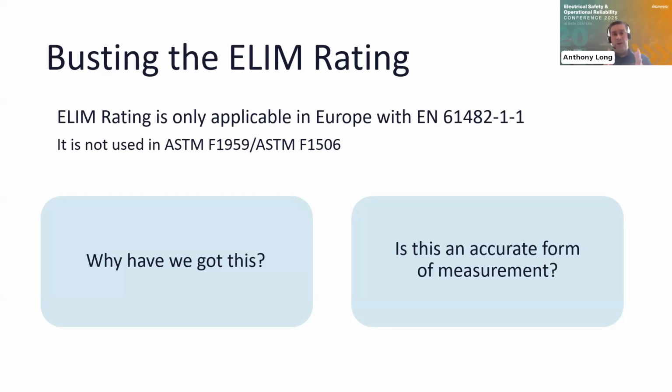The reason I don't agree with you is, we raised a question before: what arc flash PPE would you give people? And would you give people class 2 as a standard article, for example? If you have an arc flash rating that says you need 40 cal, and you have to have a 40 cal Elim garment, the 40 cal Elim garment will probably weigh twice the weight of a 40 cal ATPV garment.